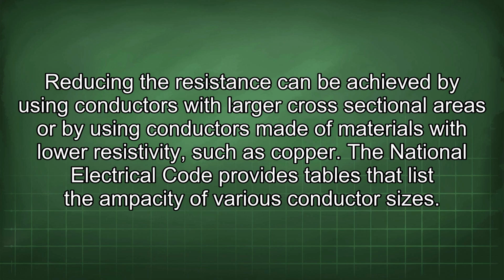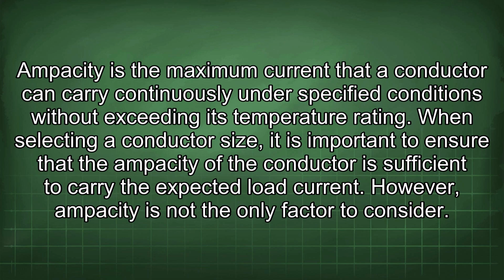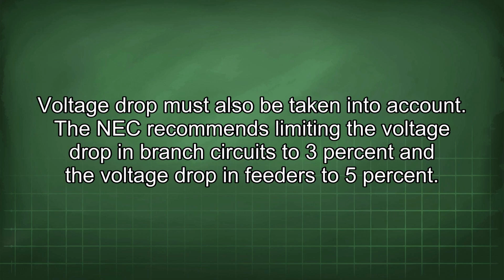The National Electrical Code provides tables that list the ampacity of various conductor sizes. Ampacity is the maximum current that a conductor can carry continuously under specified conditions without exceeding its temperature rating. When selecting a conductor size, it is important to ensure that the ampacity of the conductor is sufficient to carry the expected load current. However, ampacity is not the only factor to consider. Voltage drop must also be taken into account.